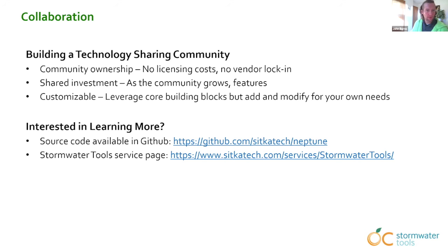I was late into the meeting, but do you differentiate between condition assessment and maintenance priority rating? In standard asset management protocols, the condition score is based on structural physical deterioration, and routine maintenance needs, such as trash, vegetation, and sediment accumulation, can be assessed with maintenance crews. Condition scores are more construction related, such as concrete pipe replacement, stabilization, and major basin reconstruction.